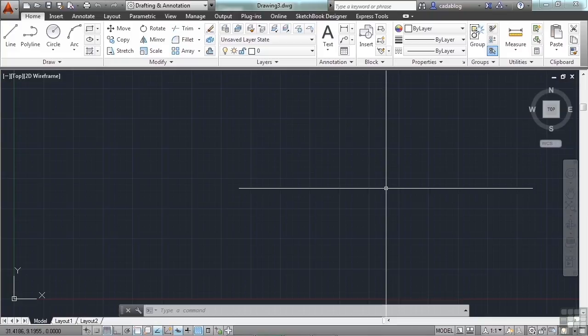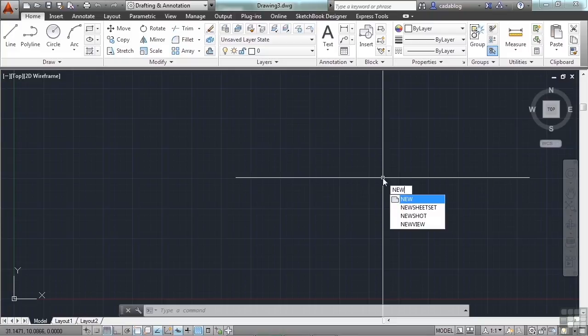Make sure that if you are using a DWG file, you first copy it and put it into your proper folder, or when you open it, perform a save as immediately. That way you're not working in that template file. That's the nice thing about DWT files. As long as you open a DWT file with a new command, you can't override the template file. So my suggestion is to use a good CAD practice of always using the new command.